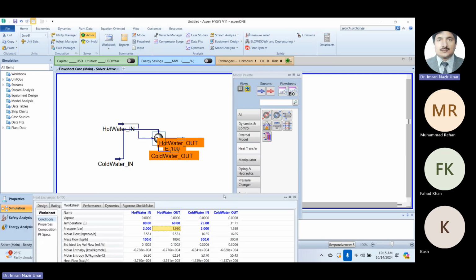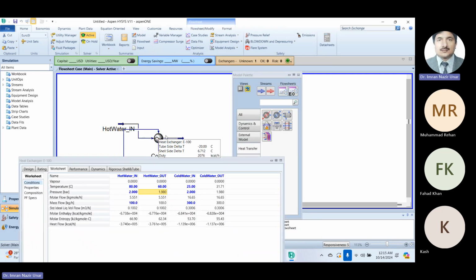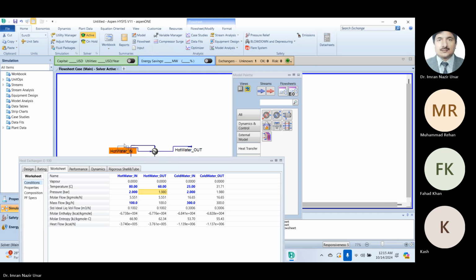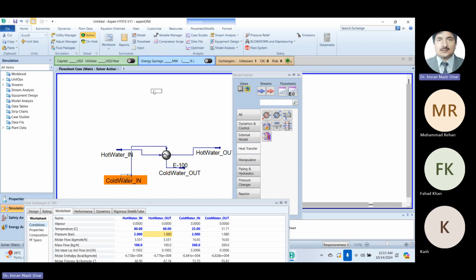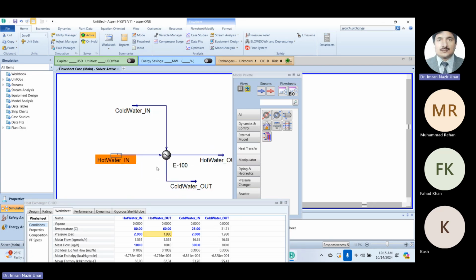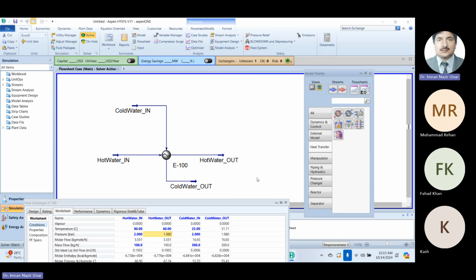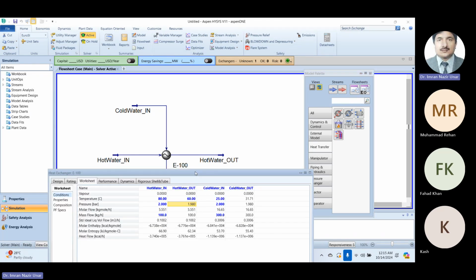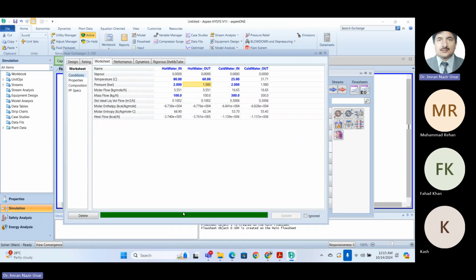On the back end, you can see now the color of everything becomes perfectly dark blue, and there is no yellow or red outline on the heat exchanger. This shape is called a completely converged heat exchanger. No problem. Sometimes convergence is there, but the heat exchanger outline becomes yellow or sometimes red as well. So we have some issues at that particular moment, but here it is okay.